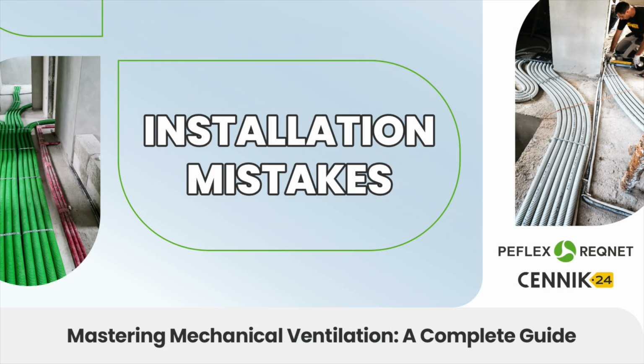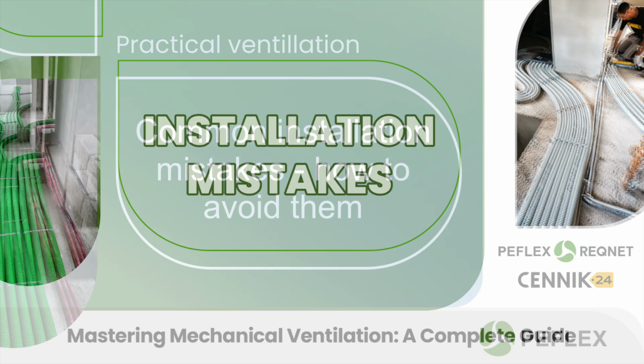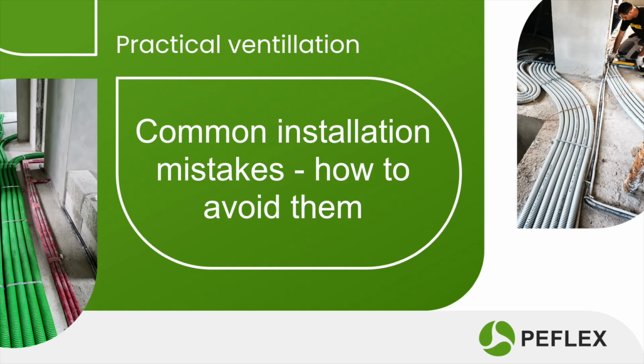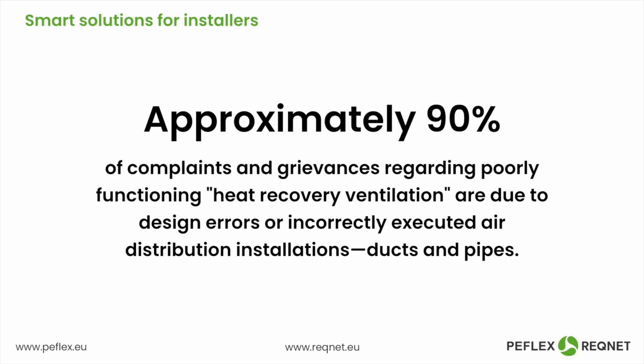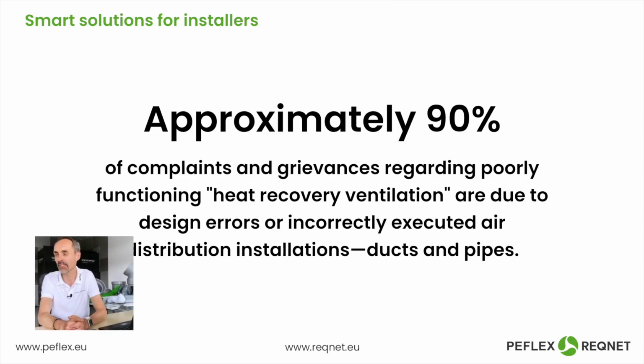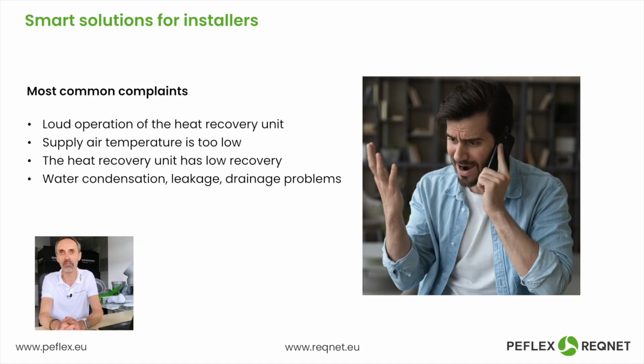Execution errors, meaning issues related to design and discussed with the contractors, yes, but things don't always go perfectly. We would like it to be that way, but there is a certain group of mistakes that are the most common because most complaints about poorly functioning heat recovery systems are related to bad design and poor installation. The most common complaints are: the system is noisy, the air coming from the supply is too cold, or water is leaking.